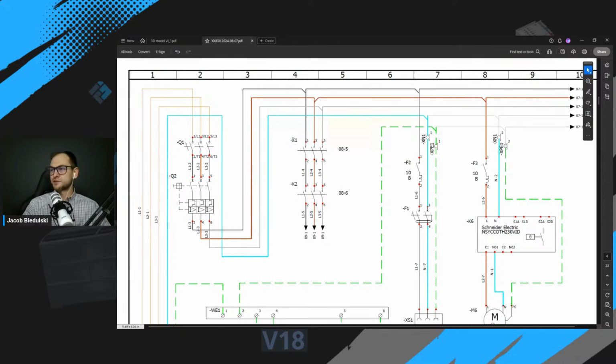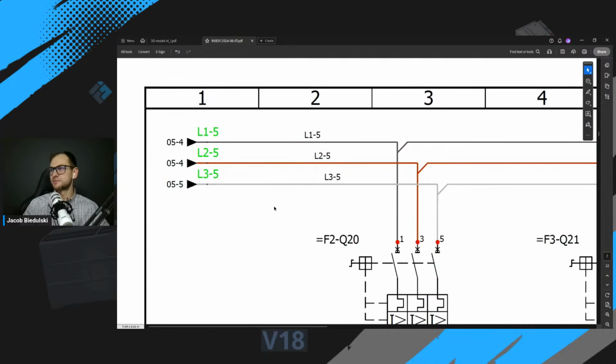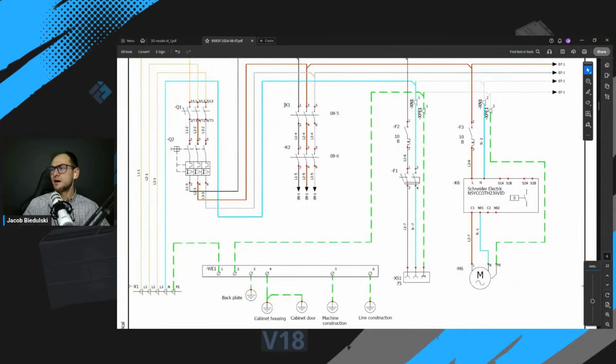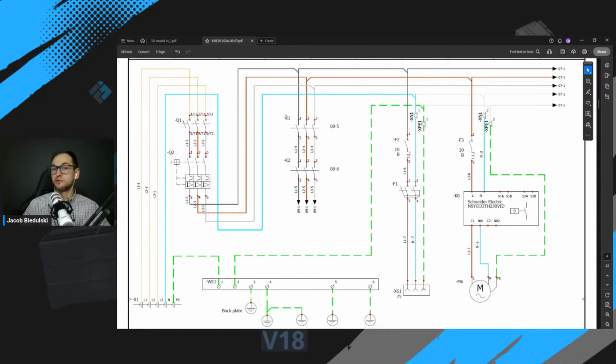Why are they connected in series, and where does the power go after the contactors? So the contactors are connected to a safety relay with e-stop function, and if the safety relay is reset, everything is fine regarding the safety system.